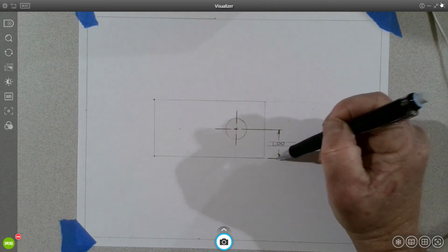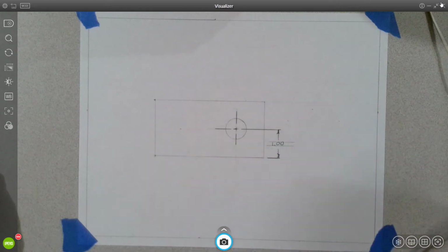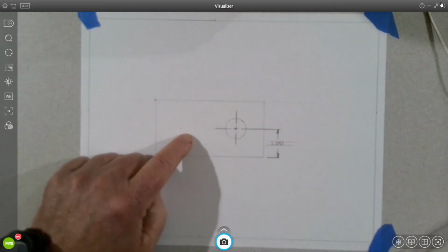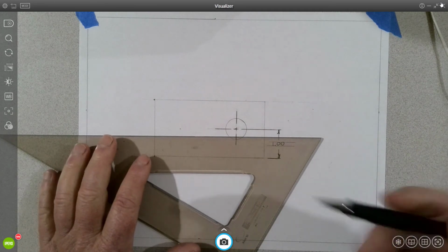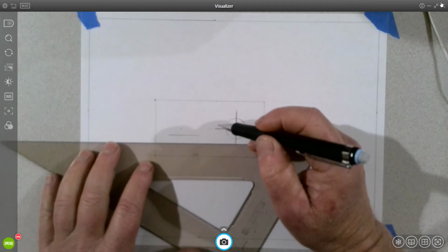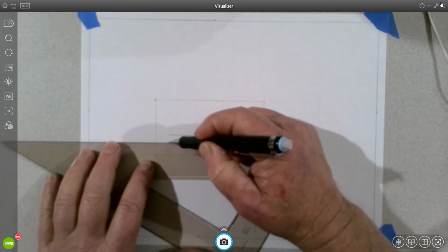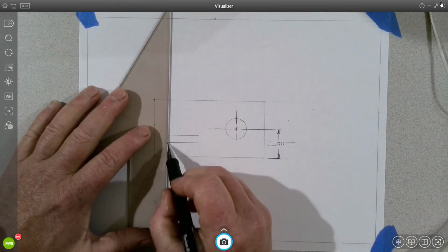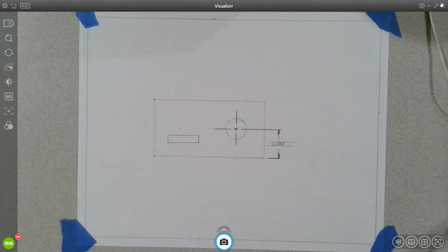Extension lines, just like this, extend to whatever they're marking. They go all the way to it. So if there was a geometry in here, a slot or something, see if I can quickly draw a slot. Again, I'm just eyeballing my parallelism, which if you're careful, this could actually work, right? So I find a vertical, go to it, and I try and just slide over. Yeah. All right. So let's say that's a geometry and I want to dimension that.